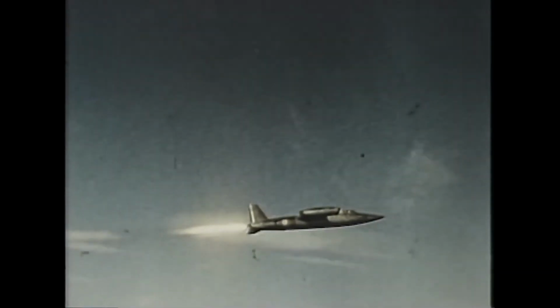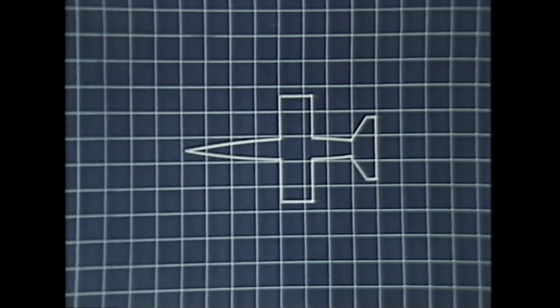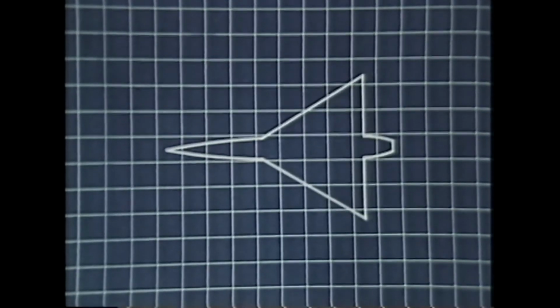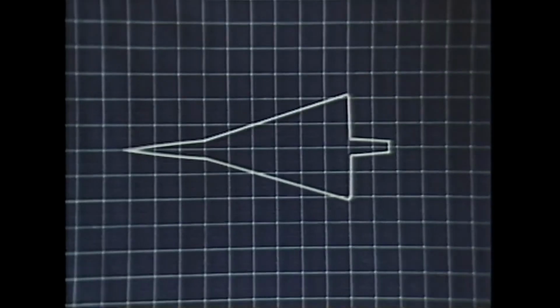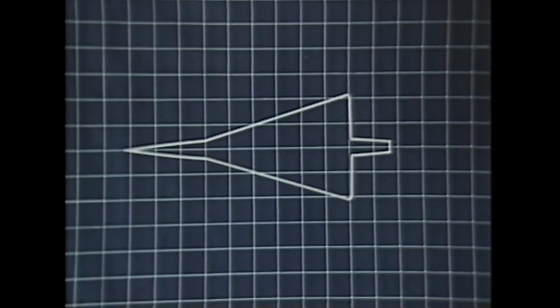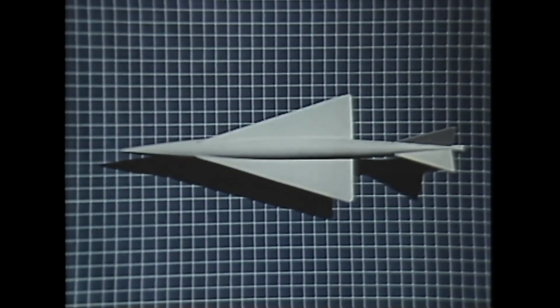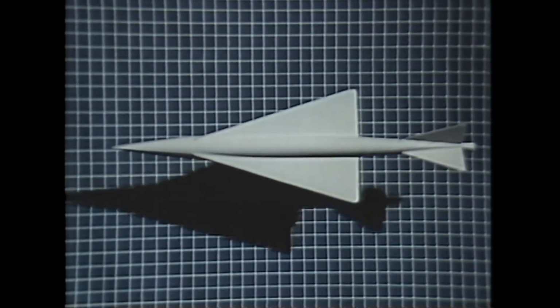But there are still a few supersonic aircraft today with straight, unswept wings using the supersonic biconvex type of wing section. And at speeds around Mach 2, twice the speed of sound, opinions are still divided about straight or highly swept wings or the delta. For the future, new ideas are on the drawing board. Vertical takeoff and landing to overcome some of the low-speed difficulties.